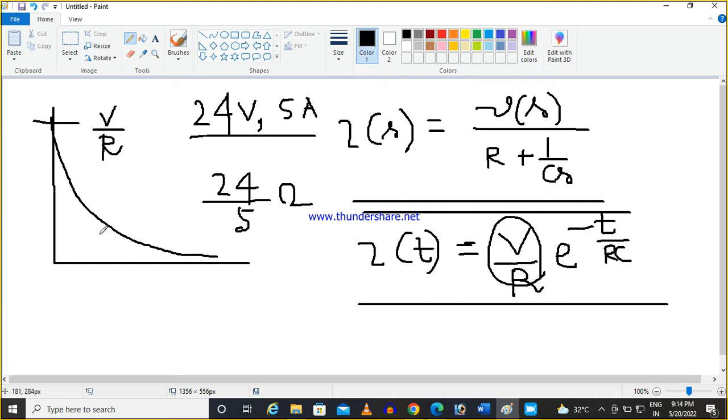So that you can reduce the power rating of the resistor, because this is not the continuous rating. You have to find out at t is equal to what time the capacitor voltage is achieving, it's a thumb rule, V by 3.